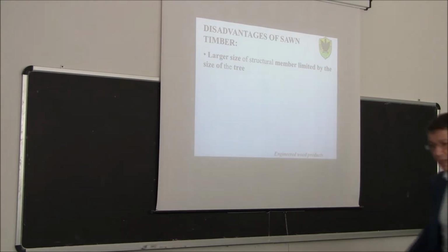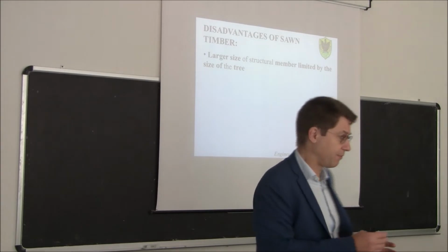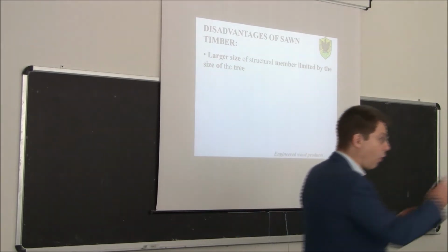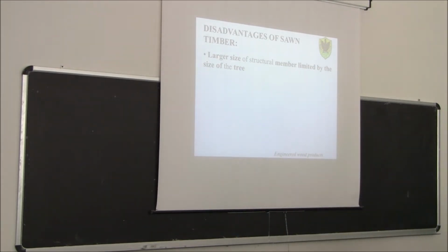So I would say that for a certain size, it's definitely better not to use solid timber, because then you can encounter lots of problems. So the first drawback: large size of structural members is limited by the size of the tree.